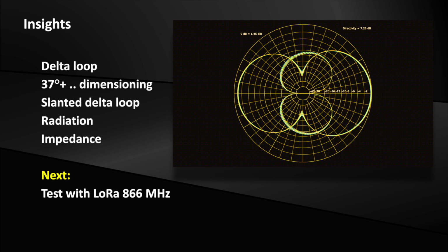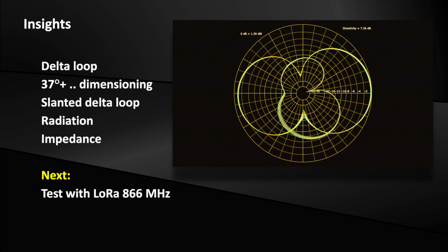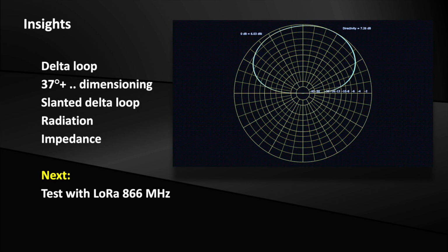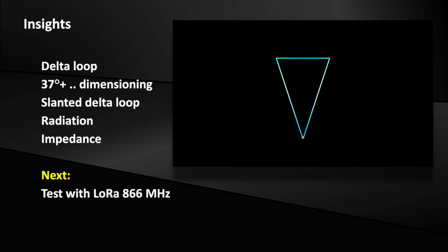You could take advantage from slightly turning the azimuth diagram to your desired direction. A low antenna height is lowering horizontal gain, an effect appearing with every shortwave antenna. In case your local conditions are not allowing for better, a tilted and asymmetric delta loop is absolutely making sense.